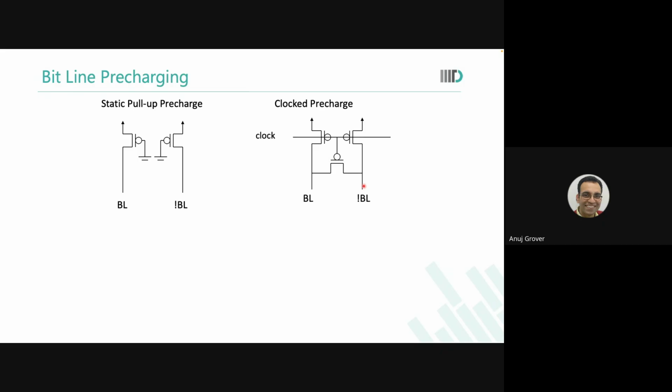Considering the write picture, one is 0, one is 1. I am ensuring there is a full VDD drop between them. But the precharge is off. There is a full drop of VDD across them.